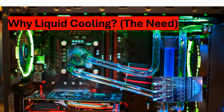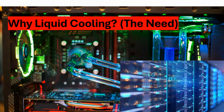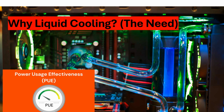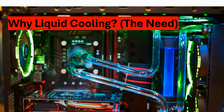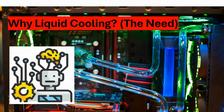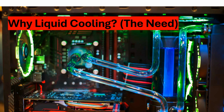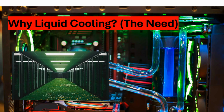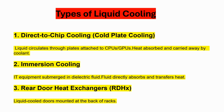Modern servers generate much higher heat compared to traditional IT equipment, and air cooling has limitations where the rack density increases beyond 30 or 40 kilowatts. Liquid cooling can carry more heat using less energy, which improves power usage effectiveness, or PUE. It also supports AI, machine learning, and high performance workloads while reducing the cooling space.